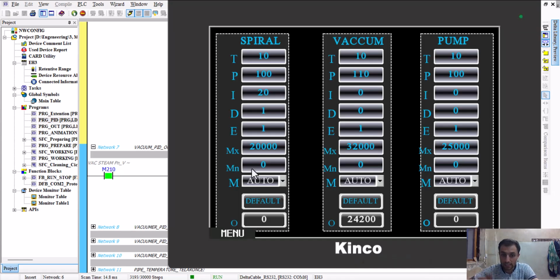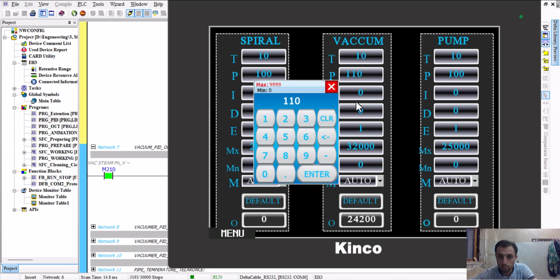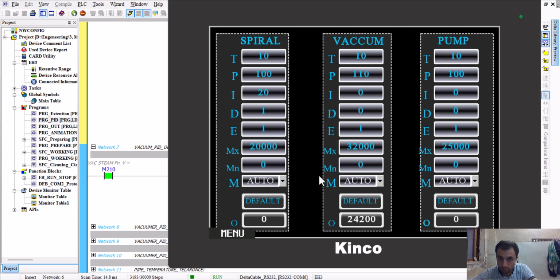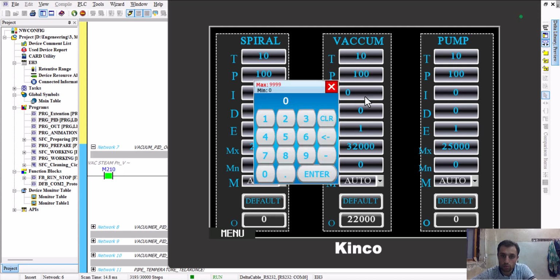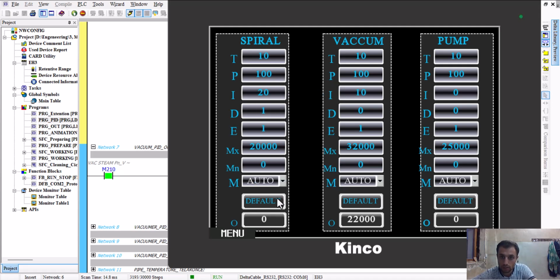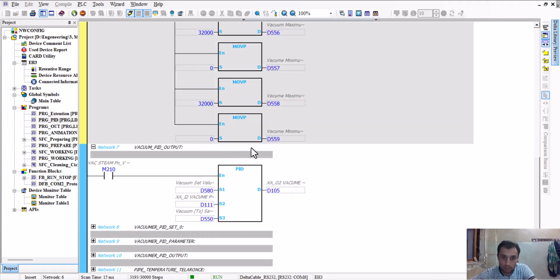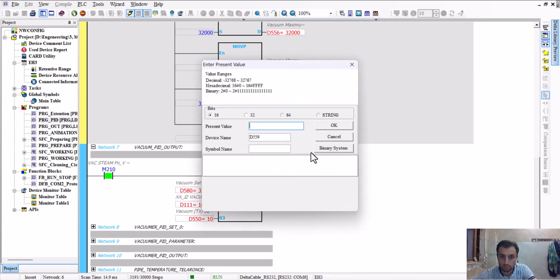How is it adding to this one? Now I will put, for example, 100% say P parameter, and I will adjust the I parameter to, this is also a percent, so I will put 10%. Okay. Now I will see 10% of this my value. Now this one I will change to, for example, 0. Understanding? Okay.